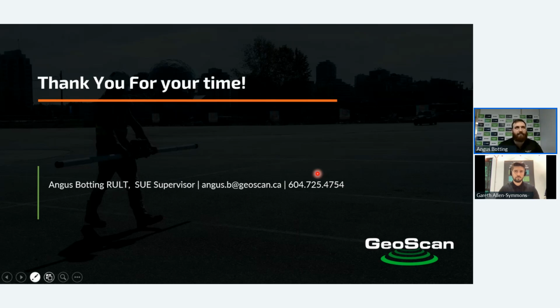It does benefit in some aspects of saving time on areas that have limited access, but the majority of the time, just the way land surveying works, they don't always pick up every surface feature that we can discover or dig out, like the manholes that we find there. So we tend to survey all the surface features ourselves.